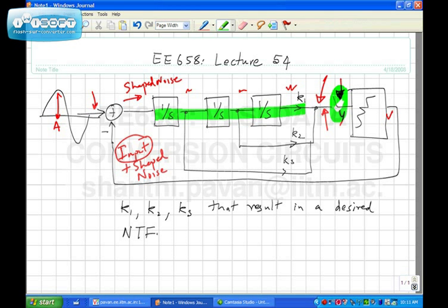But the small signal component should also have more amplitude than the shaped noise. No, why? Please note that the gain of the loop filter at low frequencies is virtually infinity. So as the gain becomes infinity, it requires an infinite stimulus. It should be more than the in-band quantization noise. Yes, definitely.